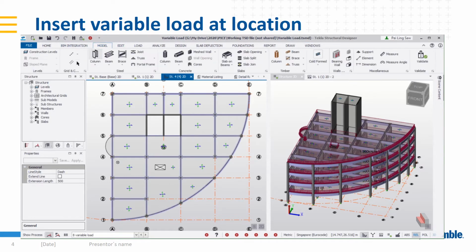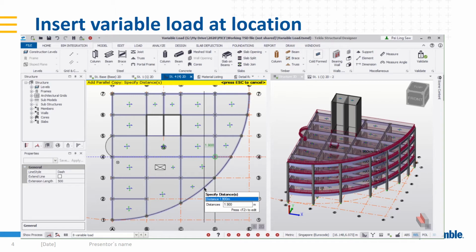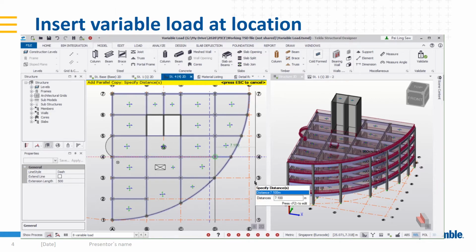In the model tab, I'm going to create some construction lines, which, if you set it up for plotting in the drawing, will not show. It's ghosted. I'm going to create some construction lines for my offsets. I'm going to use quick parallel, where I can hit the F2 button to define my offsets. It'll be 0.95, and then that's done.